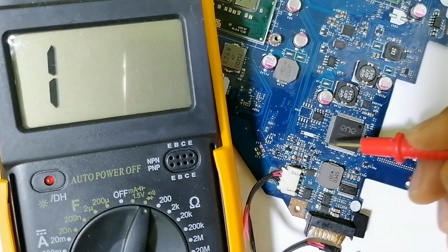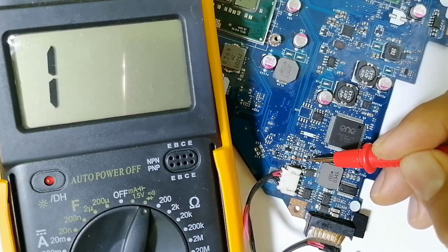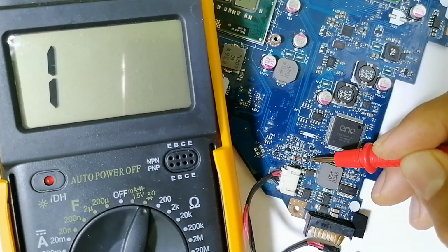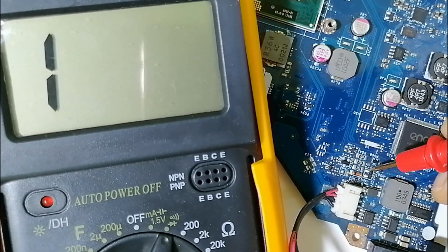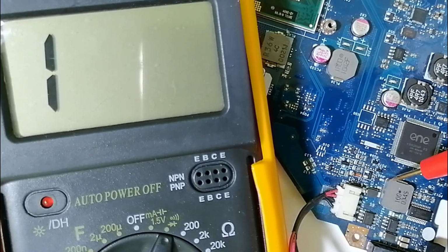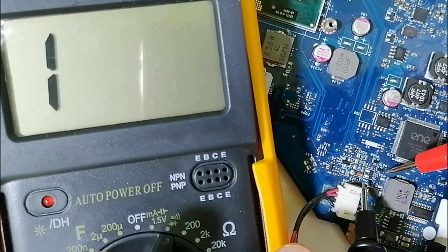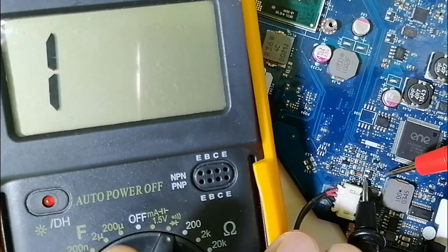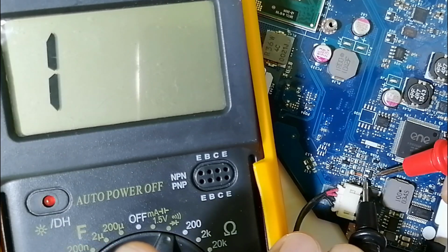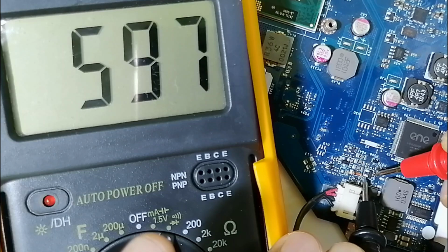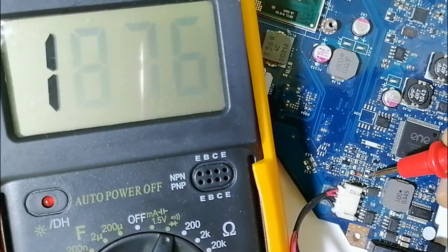So then, as you can see here, we have PQ67. This is basically a 3-terminal Mosfet. Here we have gate, source and drain. Always for this kind of Mosfet you will find gate, source and drain. So let's check it. Basically we should find a drop voltage of about 500 or 600. So let's put the black probe here on the source and the red probe on the drain. As you can see, we get 596, means this is a good Mosfet.